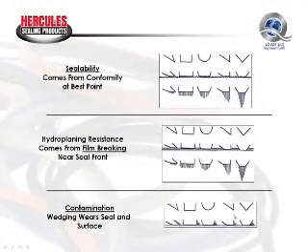The straight lip, the D lip, is good. The square lip is good because it keeps these contaminants out in front of the seal interface. And the scraper type lip is even better because it allows the contaminants to flow up and away from the seal lip sealing surface interface. Now, you might say, well, why don't we just use the B lip for almost all applications because it seals so much better?